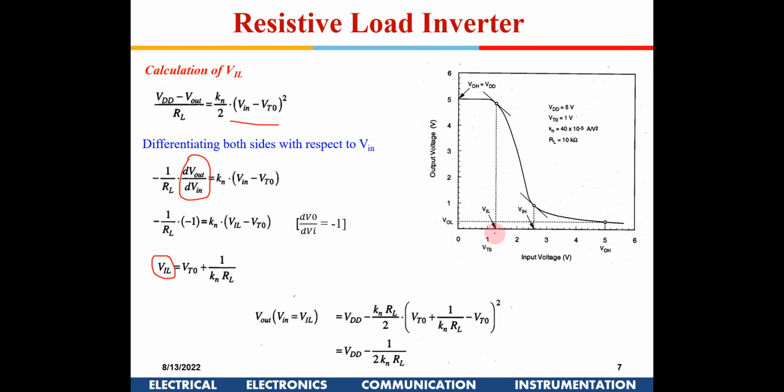So obviously if I increase this low side noise margin, it will affect the high side noise margin adversely. Okay. You cannot keep pushing it to the right without any adverse effect; it will affect my high side noise margin. Now, Kn, W and RL are inversely proportional here. So this is the equation which we get.